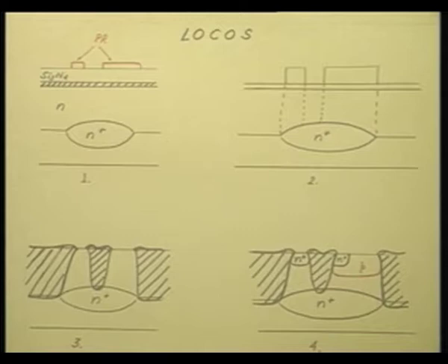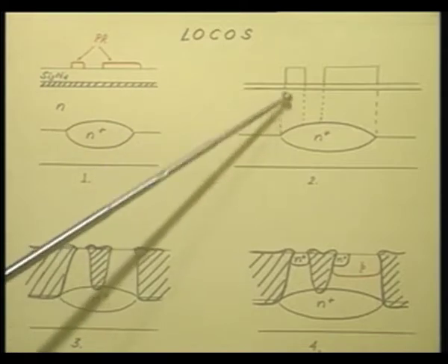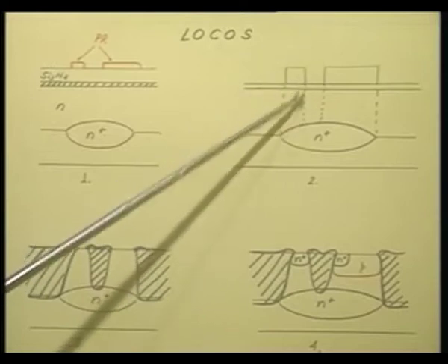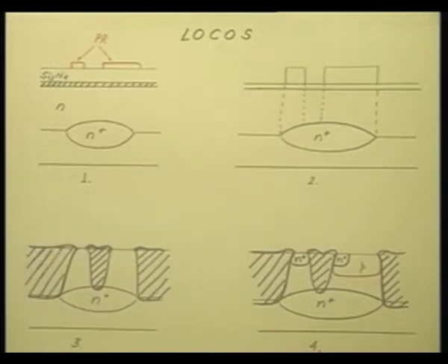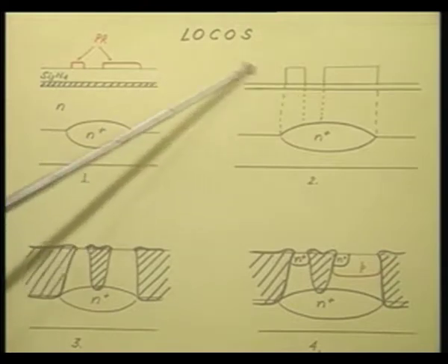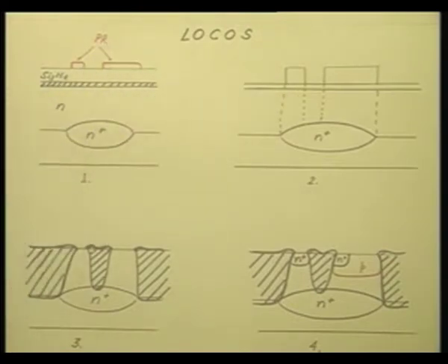So, instead of that, what is done is one additional step, as I have shown by this dotted line, you etch a little bit of silicon. That is, let us say whatever is the oxide thickness you want, you etch it down by about 0.55 times of that.